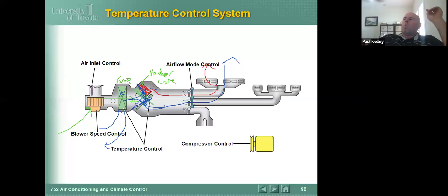So what I usually do is I'll explain it in the most simple way. And I still recommend that you think of it how I'm about to say. If the heater core gets too warm, we're going to close the evaporator. We're going to close the TXV to get the heater core cooler. And exactly what's happening, maybe not so much, because we may need more refrigerant to go through to have that refrigerant evaporate more to provide more cooling. But exactly the details, to be quite honest with you, don't really matter.